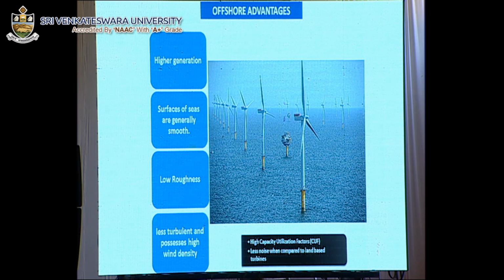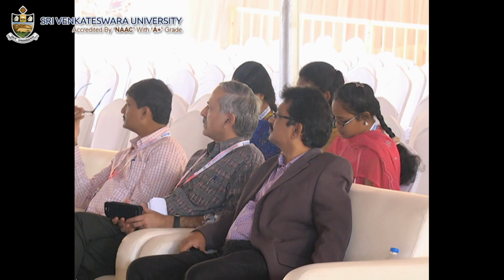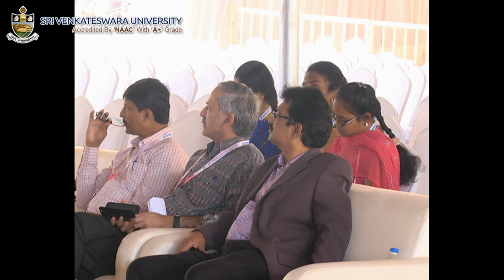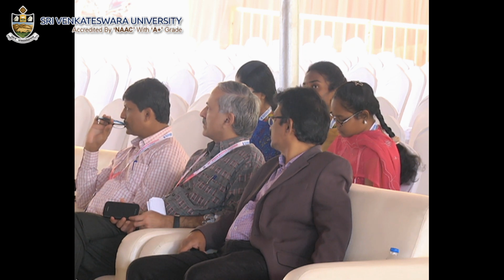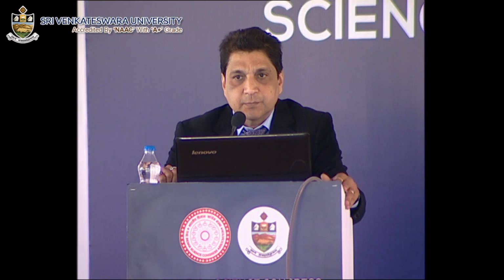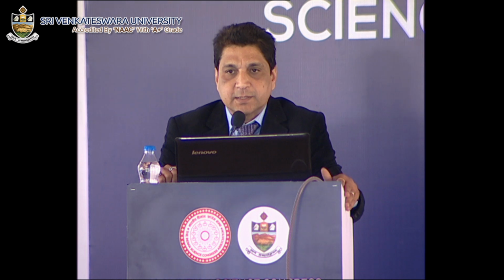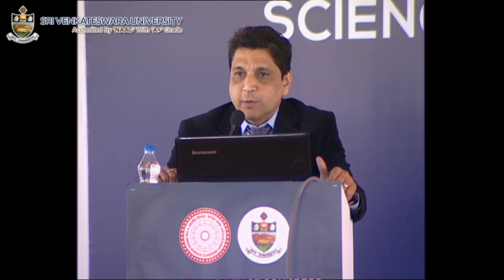Just to add to the information of the forum, normally the free flow winds blowing above the surface of the seascape are less turbulent. When I say they are less turbulent, it means the turbulence intensity is very low, which is nothing but the ratio of the wind speed standard deviation to the mean wind velocity.